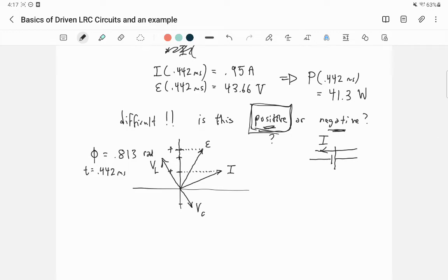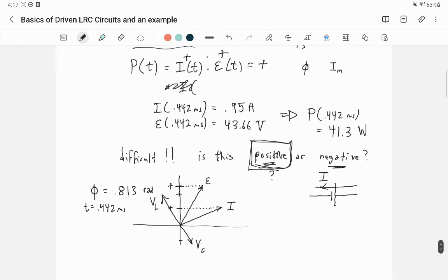Can you see that the inductor and the capacitor voltages will always have the opposite sign unless they're zero. When they're zero at the same time, which is interesting. Okay, so anyhow, here's a waypoint. I wonder if you can end up calculating that that's the power. And this is approximate. I wasn't keeping track of significant figures too carefully, but it's around 41 watts.